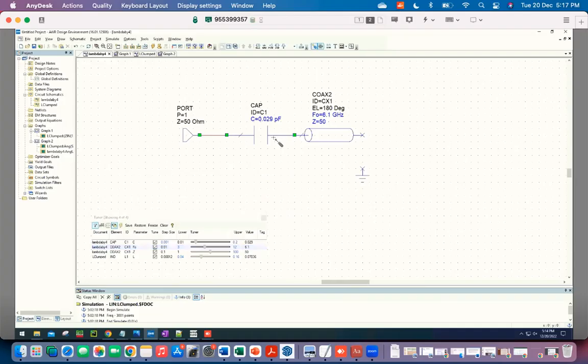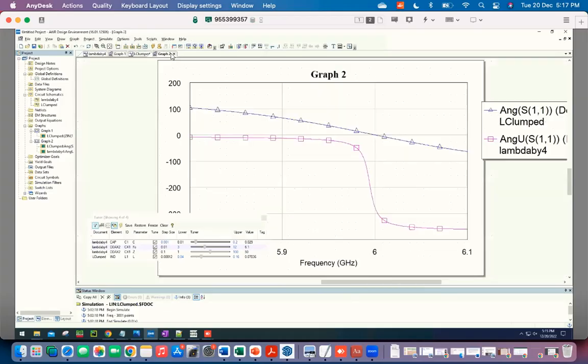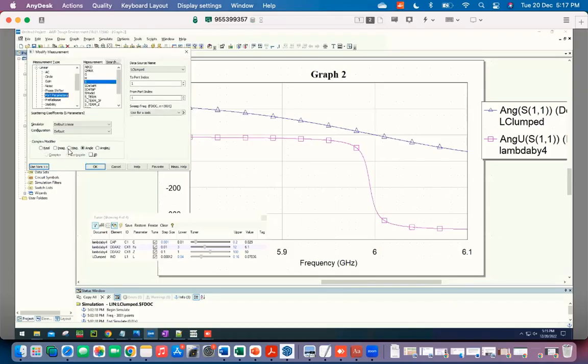Now, coming back to this, all you had to create was some kind of an impedance mismatch, right? So you can do that with an inductor as well, or some other combination of inductors and capacitors, as long as it is giving you the right impedance at the relevant frequency of interest. This would work fine. You can also play with the Z0 to some extent, which is allowed, within this 20 to 100 ohm range, and that will also affect your Q factor. So if I now look at the same resonance, let me go back to here.